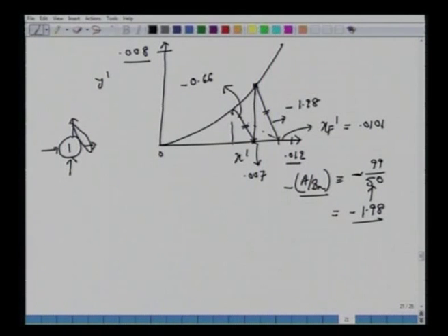So read the raffinate concentration of the second stage. So now we are here. Stage 2. Read this number as 0.005. So in the first stage we have reduced the concentration from 0.012 to 0.007. In the second stage, we have brought it down to 0.005.